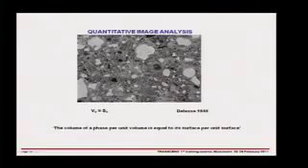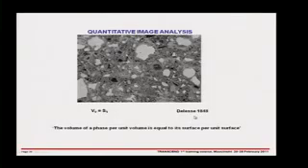And it's been very, very long established in 1848 that if you have a statistically representative cross-section, the surface you measure on a surface is exactly equal to the volume in a volume. So people always ask me this question. They say, if you're only measuring the area of that unreacted cement on a smooth surface, how do you know that's equivalent to the volume? Well, I know because this guy Delesse proved it in 1848.